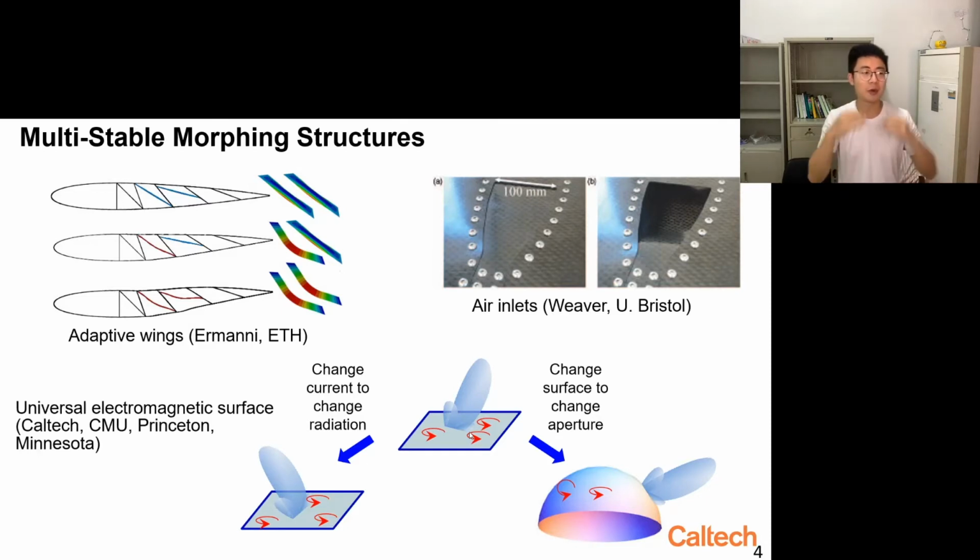Let's imagine we have a phased array antenna put on a flat surface. It can generate electric currents and radiate electromagnetic waves in the normal direction very well, and it can steer a little bit, but it cannot see very well to the side, because the projection area is largest in the normal direction but minimum to the side.